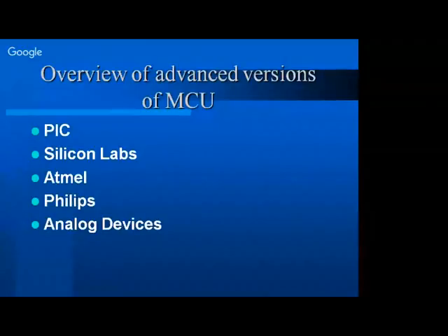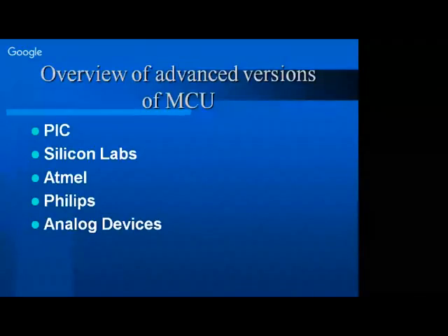And at the same time, PIC also brought in many things like RISC, Harvard, pipelining, so therefore a lot of performance to the chip. PIC also gave a kind of thing where every instruction can be performed within 1 or 2 machine cycles and would consume just 1 or 2 bytes of code. So this is how every chip has got some story to it, and therefore selection of each controller will mean something to you while you develop any kind of industrial applications.